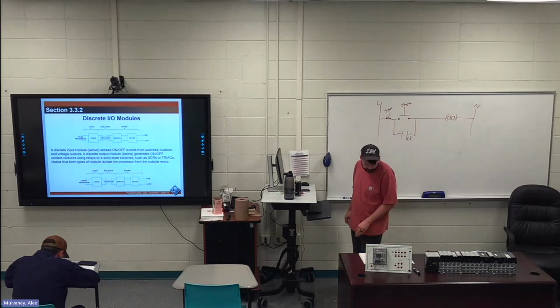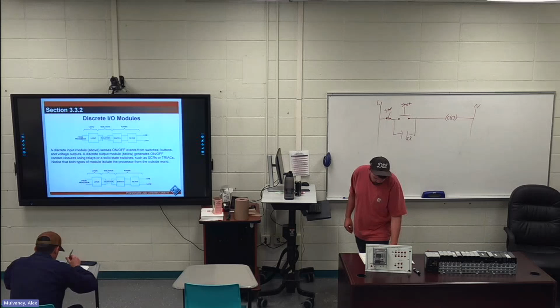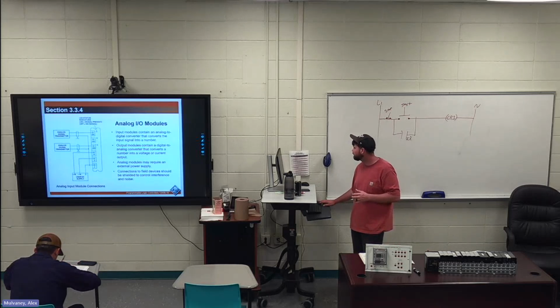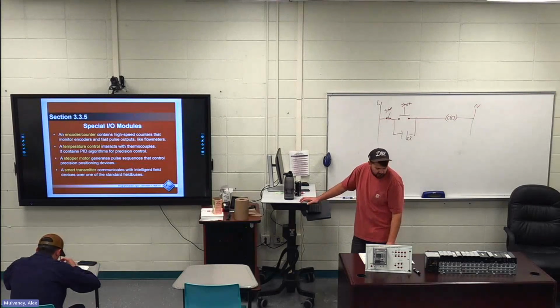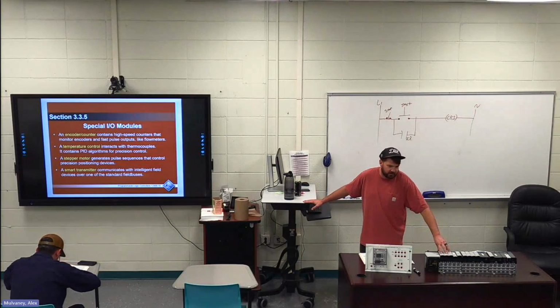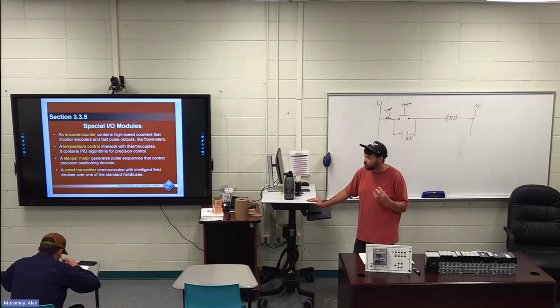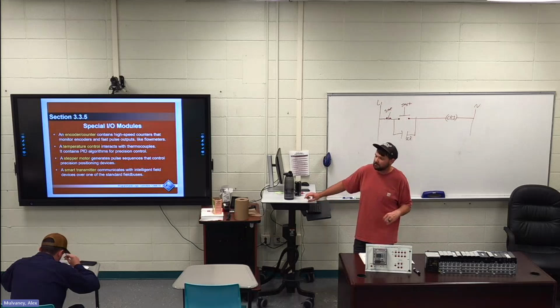The highlight that I have is the second paragraph, first sentence. Really, you need to read through those two paragraphs. These are interface modules for things like encoders, right? Stuff that's going to have large bits of information coming probably in hexadecimal. It's not going to be discrete information that's just ones and zeros. These are large words or large bits of information coming super fast. It's not somebody pushing a push button. It's something spinning or something that's creating a large amount of code all at once.